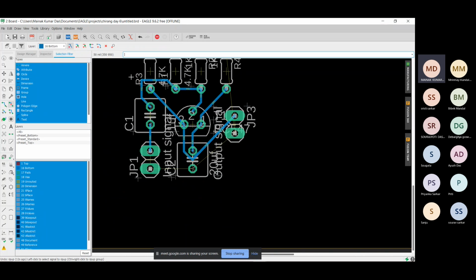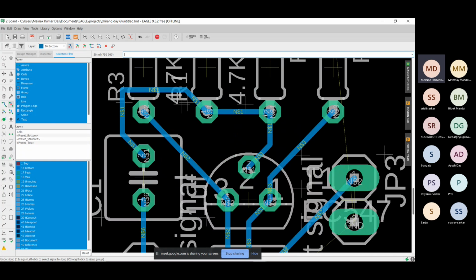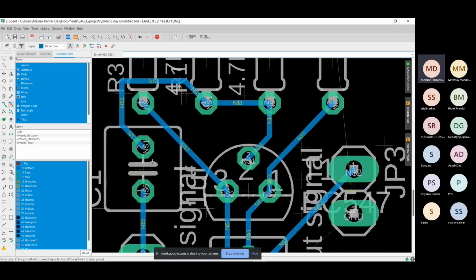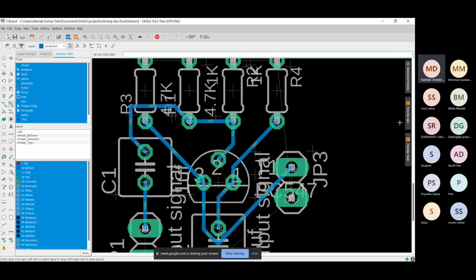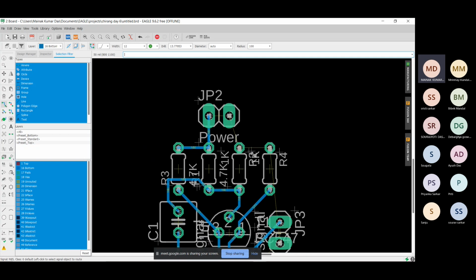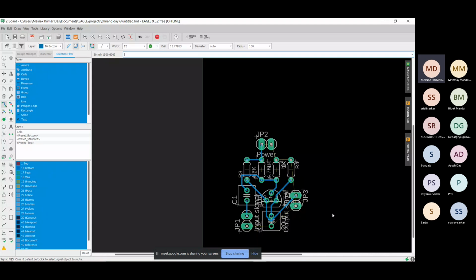So just see on the resistance portion, capacitance portion, and at the upper section. Yes, this is ground, this is ground, this is ground, and this is not ground. So wherever you cannot find the ground, you just add it with the copper traces or net.